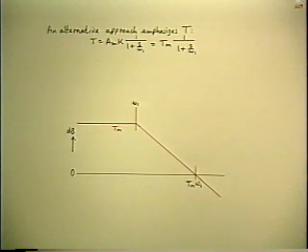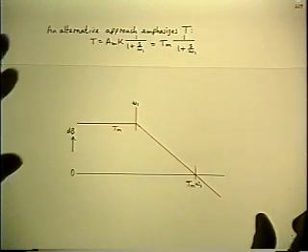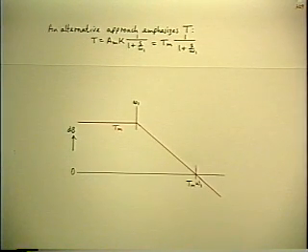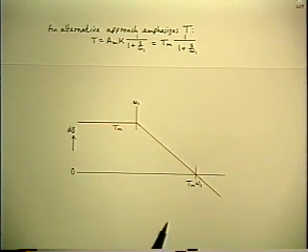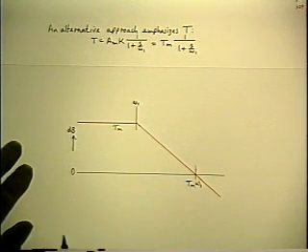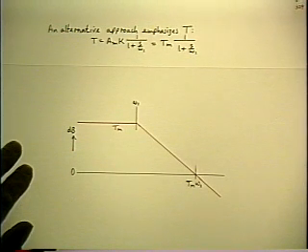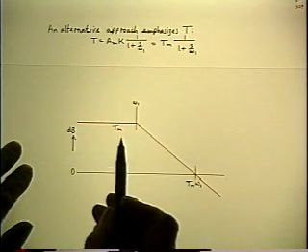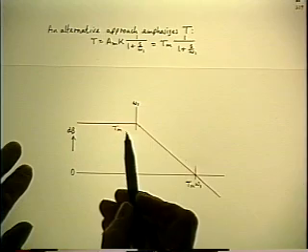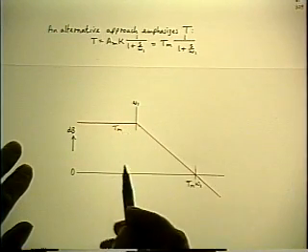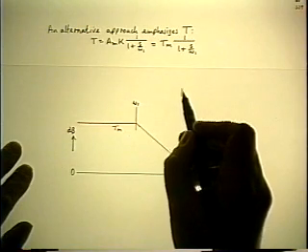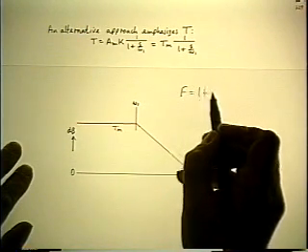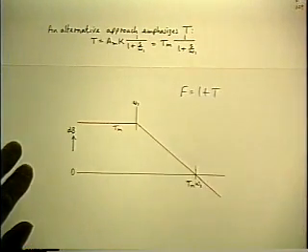So I'm going to do that graphically on this picture by a procedure which I already used in the example earlier on to do with why a right half plane 0 can show up. Down here, T is large. Now I'm trying to construct F equals 1 plus T, which is adding two functions.